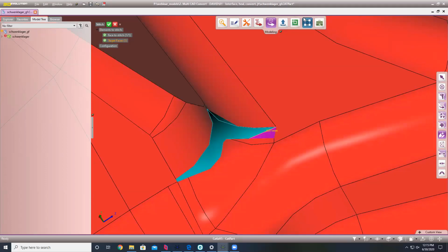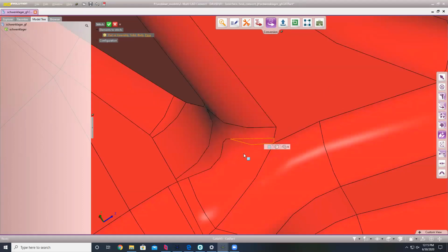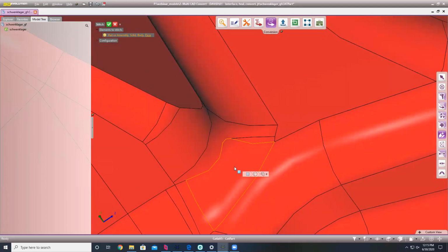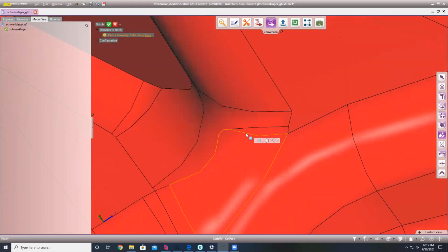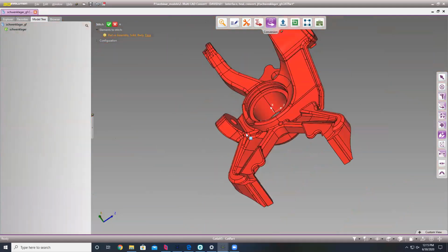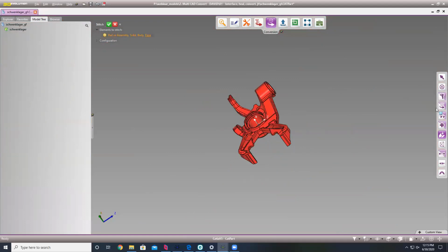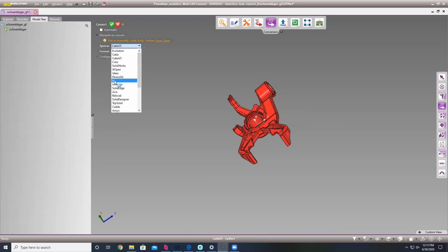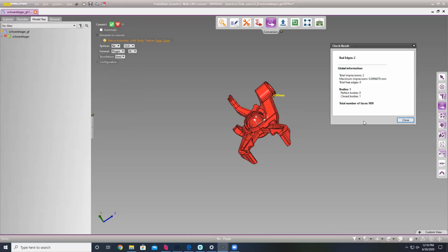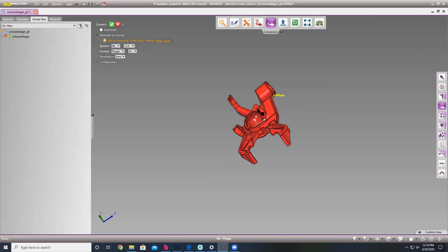And so we chose the original face and then we chose to stitch the second one, and now it's a clean model. Let's do the exact same thing, but now let's write it out to NX. So for those that are in the CAE department, they know that either a Parasolid or an NX file is going to have additional free edges.